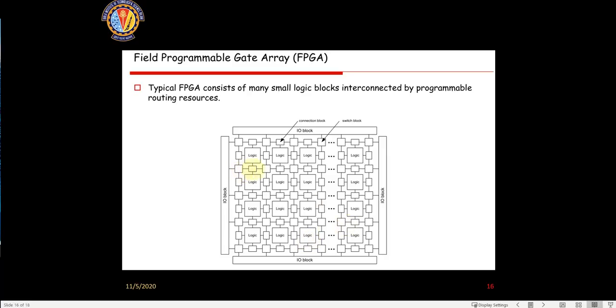Okay, and also these are all small interconnections. So the Xilinx will also program these interconnections; they are also programmable, right? If this particular block is one module, you have made it as a D flip flop. The other one could be an AND. So these need to be interconnected also, right? All these interconnections will be programmed. So you don't have to do anything. You just write a code in Verilog, and it will program this FPGA, right? So till now we have learned how to program in Verilog in Xilinx.